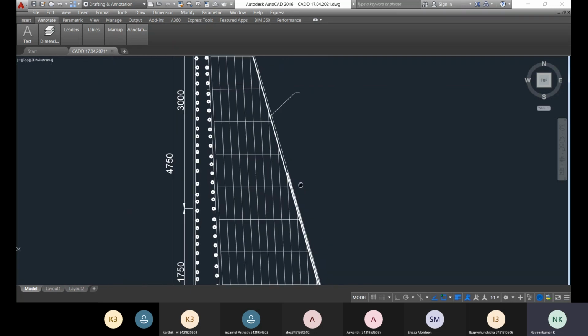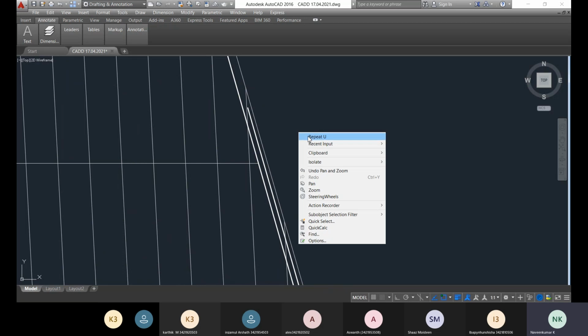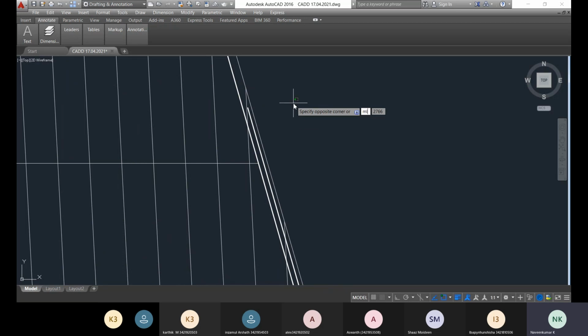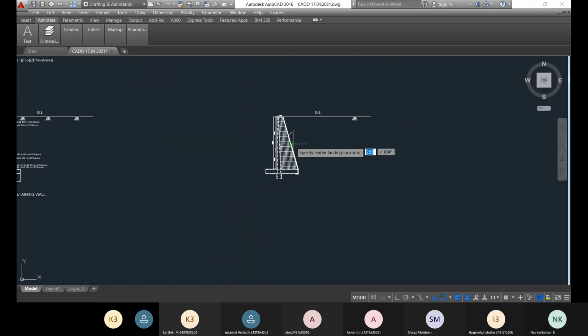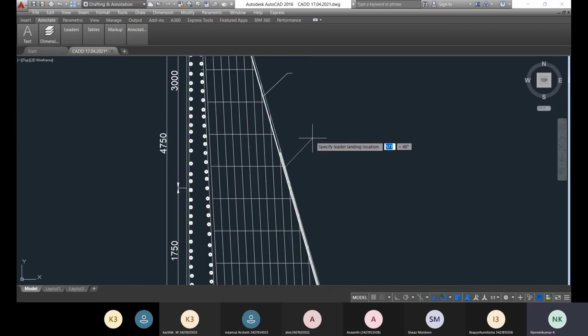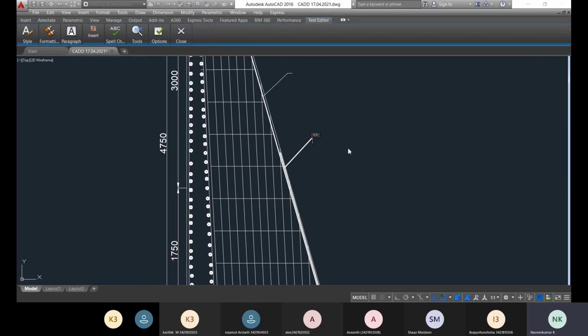After that, for the second curtailment detailing, you repeat the MLD. MLD is nothing but M leader. You choose the secondary. So that is the bottom curtailment detailing. The bottom curtailment detailing is chosen. Then you detail that one also. So what is the detailing for that?